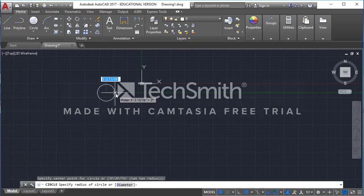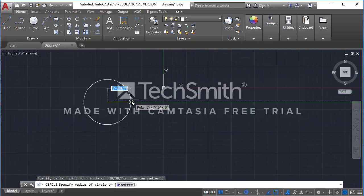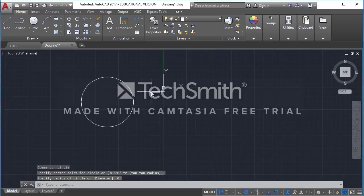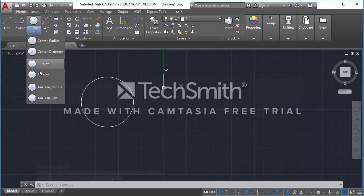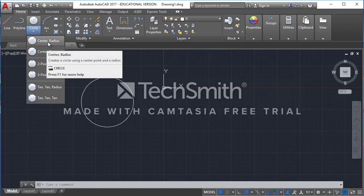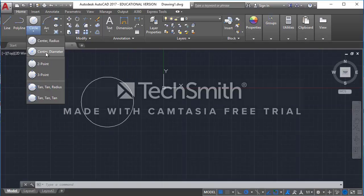When I click on my circle, notice that the circle gets bigger, but what it's asking me to do is put in a radius. As I get bigger and bigger, it's saying that my radius is about 6 feet, 7 feet, and I could input any dimension that I want, and I'll get a perfect radius. If you click on the little drop-down menu under circle, you'll get different options for how you create the circle. The first one is center radius, which is the default in AutoCAD. The second one is center diameter.